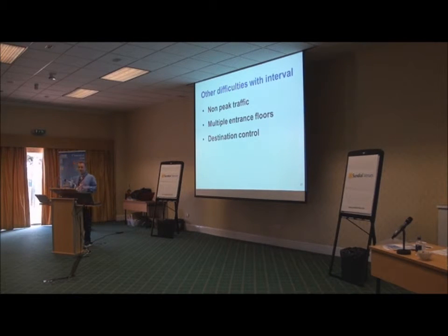So there are some other difficulties with interval. Non-peak traffic, and I'll refer to Coney. You've got some good things with non-peak traffic with round-trip time calculations, really interesting. But again, because I do simulation, I don't worry about that and just go straight to simulation. Multiple entrance floors can be complicated with round-trip time calculations, because if you've got 6 entrance floors and you define interval as the time between departures to the main terminal floor, well, actually sometimes you go past the main terminal floor. There's a good paper from Dr. Powell, Bruce Powell, about that, multiple entrance floors, some issues there.